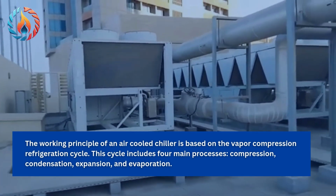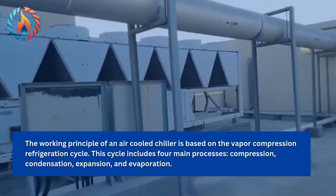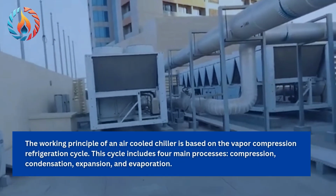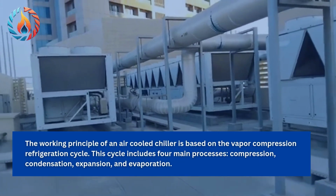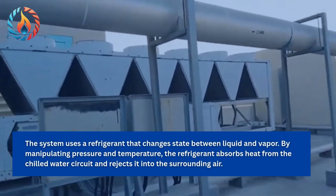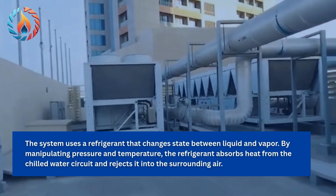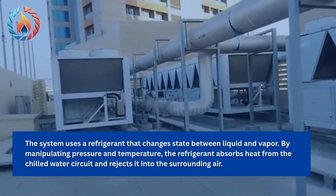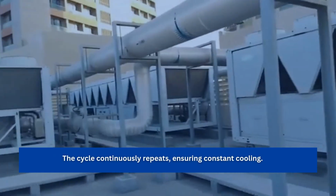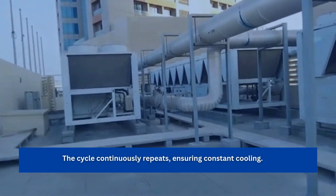The working principle of an air-cooled chiller is based on the vapor compression refrigeration cycle. This cycle includes four main processes: compression, condensation, expansion, and evaporation. The system uses a refrigerant that changes state between liquid and vapor. By manipulating pressure and temperature, the refrigerant absorbs heat from the chilled water circuit and rejects it into the surrounding air. The cycle continuously repeats, ensuring constant cooling.